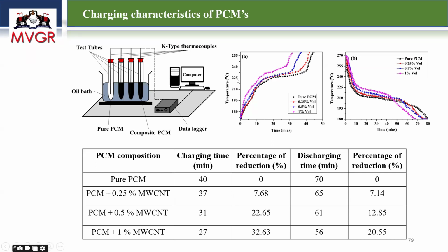If you conduct this experiment, what I'm doing here is putting in the various PCM materials and heating them up. Here the charging time is significantly reduced. From the time versus temperature graphs, you can see that. We are adding this multi-wall carbon nanotube. This is the pure PCM, which takes a lot of time. Suppose for 20 minutes it reached around 220 degrees centigrade. But